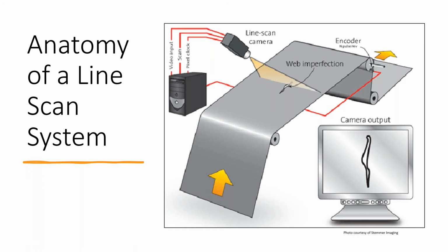But no matter what type of defect you have, it's important that you consider what lighting has, as that can vastly change what contrast you have, especially given the environment that you may be operating in. If there is overhead lighting or other indicator lighting, it's important to account for that when we're looking at lighting, because we want to make sure that we are able to give as much light as possible to the camera, because truly the faster that we can run the line, the higher the throughput. And that really comes down to having a higher intensity light and being able to sustain that for a long period of time, which is why it's crucial to have really solid lighting for your line scan applications.